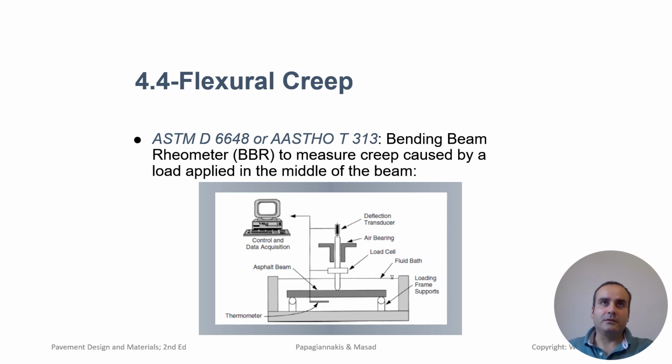Stiffness is one of the parameters obtained in this test, where a low stiffness value indicates better low temperature flexibility, reducing the risk of cracking. M value is another parameter obtained in this test. A higher M value indicates a binder that can better relax stresses at low temperatures, improving its resistance to thermal cracking. The BBR test is crucial for predicting the binder's performance at low temperatures and its ability to resist thermal cracking.